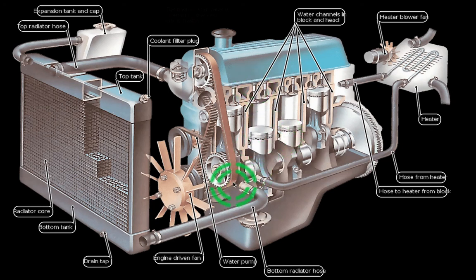Okay, so do not remove your thermostat. If you've done your build and it heats up and it's race spec, you can go for a lower rating, lower degree. Like we've done 68 and it's beautiful, especially for Dubai. 68 is good even for stock cars, because it allows the thermostat to open slightly earlier, so it maintains a good temperature, like what you see in European countries.